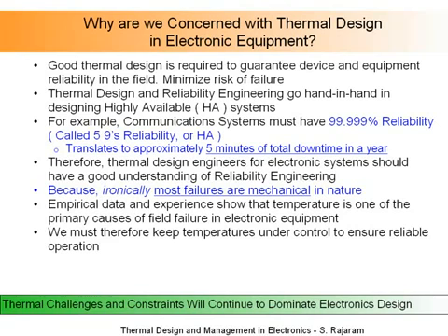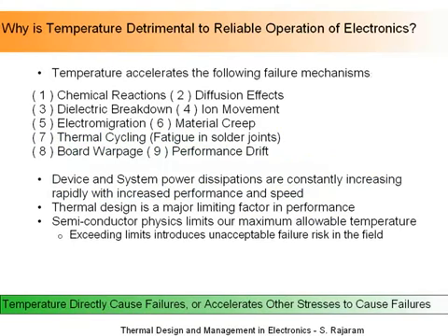Now, the next question is, if temperature is important from a reliability perspective, what is the impact of temperature and why is it impacting reliability? The reason is, with experience in the field over the last 40 years or more, we know that temperature accelerates all of these failure mechanisms that I've listed here. I'm not going to go through each one of those, but just to give you an idea that all of these failures that we see in the field, which have been very thoroughly analyzed and understood, tend to be driven by temperature.